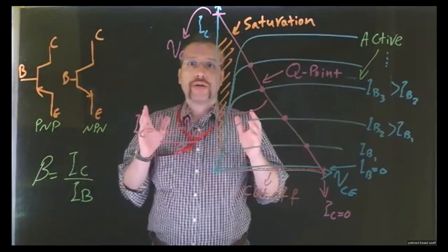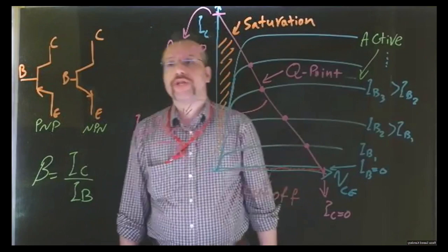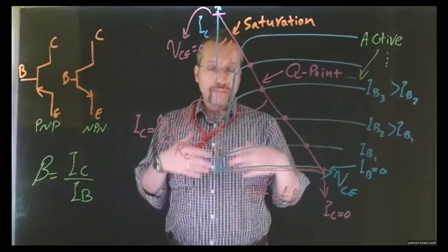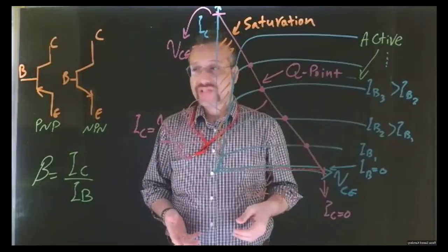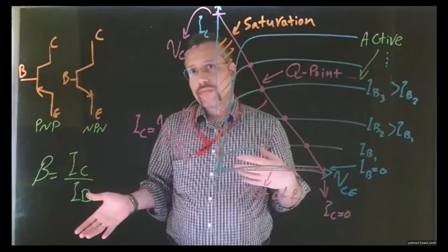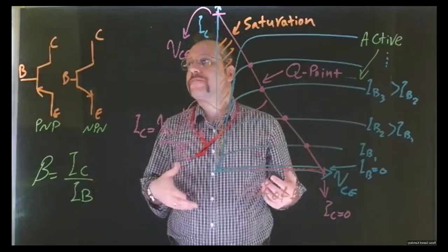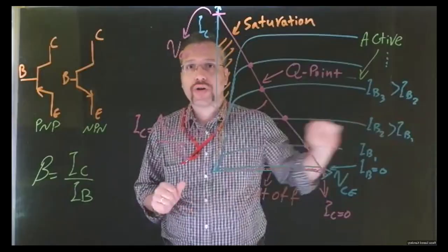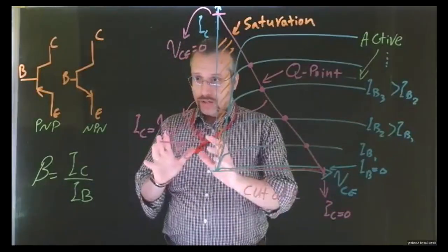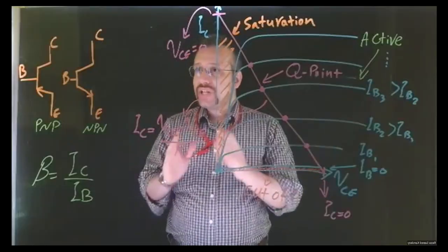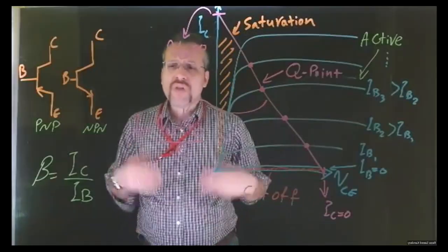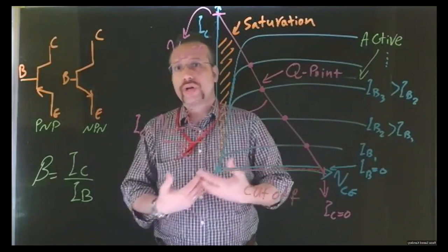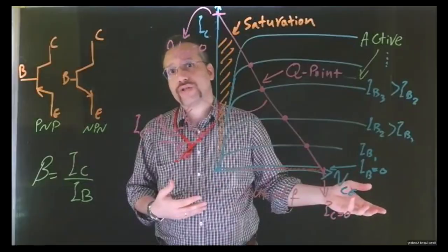Okay, let's start the new conversation. In this part, we are going to talk about the BJTs, or bipolar junction transistors. They are different from the MOSFETs and basically the FET transistors. The main difference, besides the physical structure of those components, when we talk about the application, is that normally when we talk about triggering a FET, we need a voltage to trigger the gate of a FET transistor, okay?